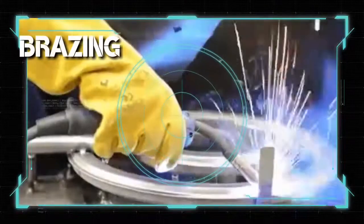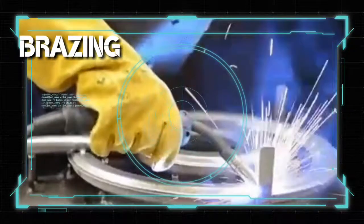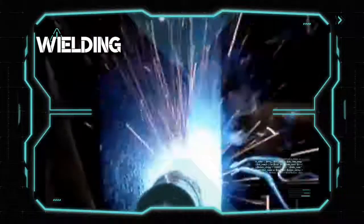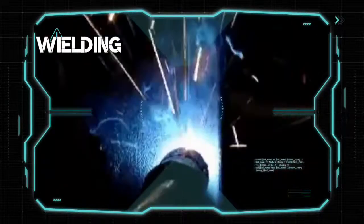We have also brazing. Brazing is a type of soldering in which the operating temperatures are higher but lower than in welding, in which stronger or higher melting alloys are used to fill joints. Also welding. Welding is the process by which two metals are so joined that there is an actual union of the interatomic bonds.